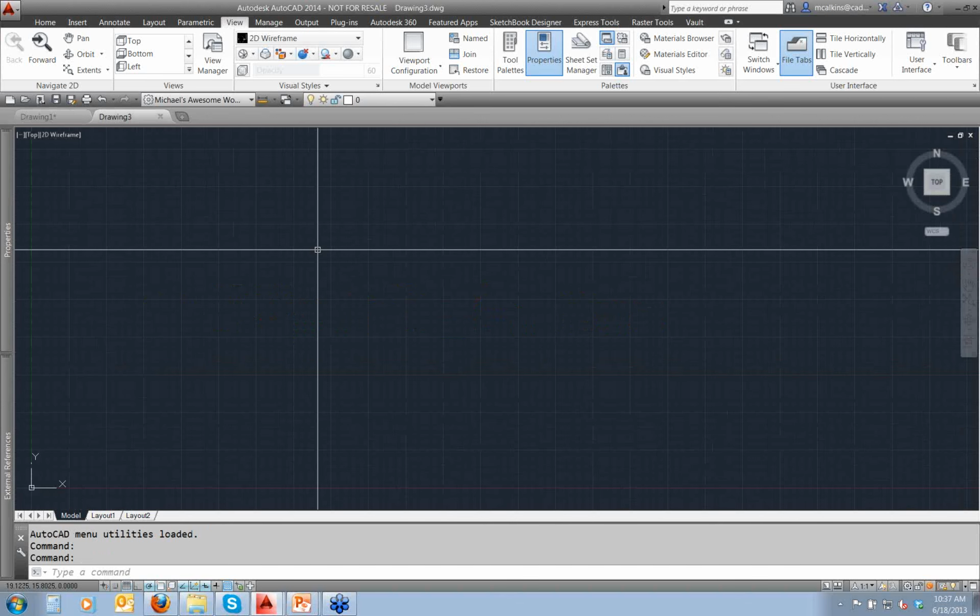So what this means is that if you only do 2D drafting and you're not using the view cube, you need to go into your company template, open up the template, and turn off the view cube in the template. Because if it's on in the template, every file you create from that template going forward will have the view cube turned on. This is a per drawing setting. Why? I honestly can't say. I guess it's because sometimes people work both in 2D files and 3D files, and you want to be able to control it per file rather than globally.